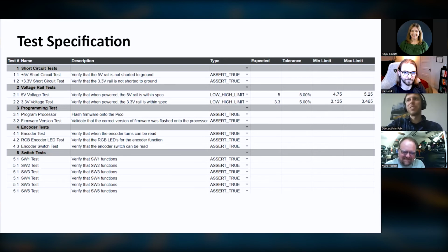Yeah. And especially with tests, if you have a test-specific set of firmware features or something like that, someone will throw a new version of firmware that gets programmed onto it. And then all of a sudden certain tests will start failing sporadically. It's almost always down to something weird changing and causing some unexpected behavior on the microcontroller. Making sure that the firmware you developed the test with is the same one that's being run in production is very important. So yeah, always do it. It doesn't take any time and it'll help you.